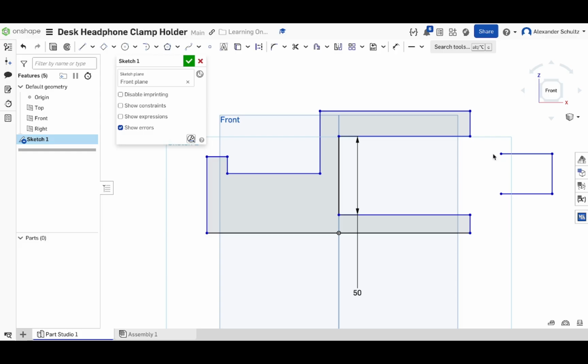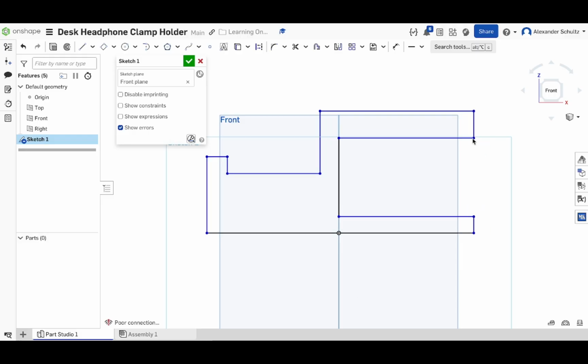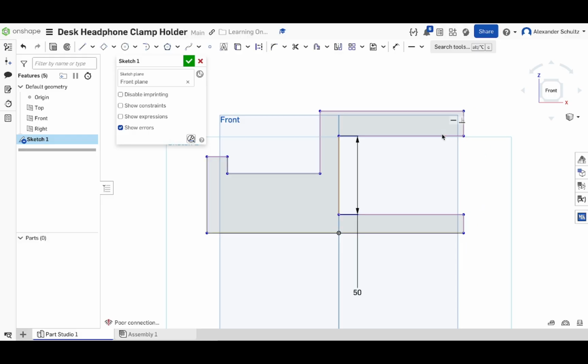This is a bit different from vertical of a line because there's no line there, but you can vertically or horizontally constrain points, so those points are vertical or horizontal from each other. Yeah, so just make a note of that. That's why these move in tandem, because these points are vertical, which you can see by hovering over, and then you can see the vertical constraint that is applied, and the two points that are on that line.